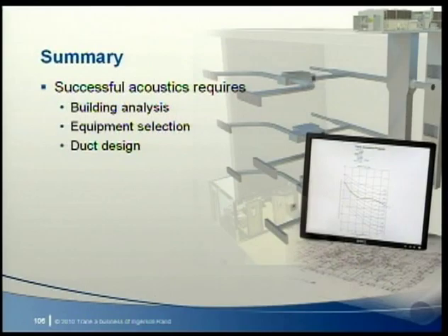Another common feature of problem jobs is large aspect ratio ducts. These ducts are well suited to transferring low frequency sound into the building. If possible, replace the single large duct with multiple smaller ducts from the unit. And finally, locating air moving units away from sound sensitive areas is always a good idea, but it is even more important when duct compromises are likely to be an issue.